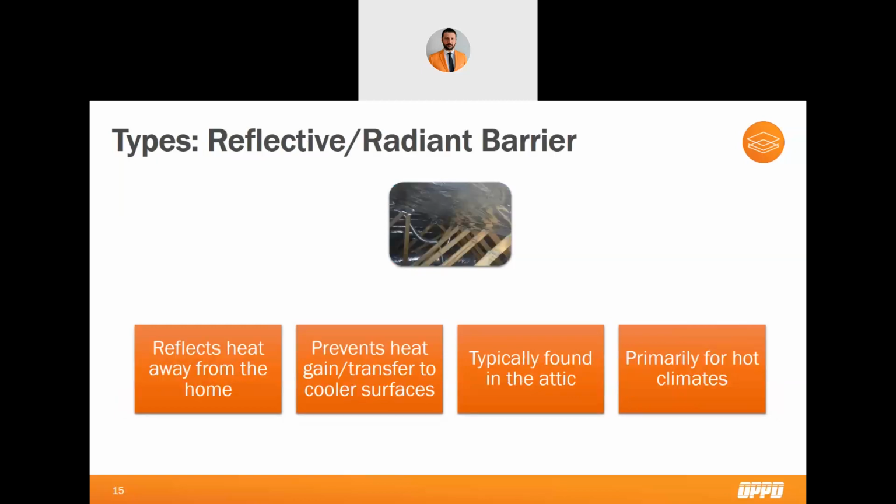Radiant barriers are a little different breed of insulation as they are more for reflecting heat away from the home. Essentially, they reflect heat radiation coming toward them and impede the heat flow by being poor emitters of heat radiation. Now, with that being said, a radiant barrier's R value does drop quite a bit with air convection, that is, air traveling via a gas. This presents a problem in using radiant barriers as insulation. In order for them to be effective as insulation, they must face a calm airspace, essentially one without air convection, though it is difficult to achieve.